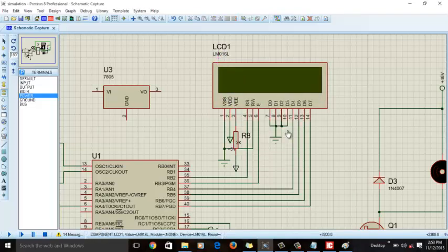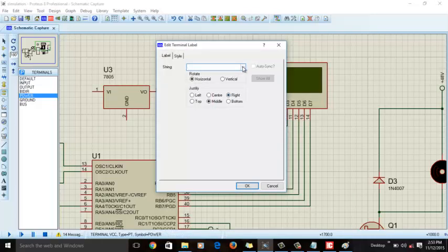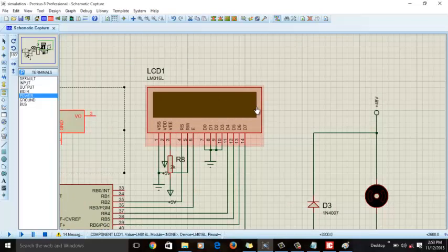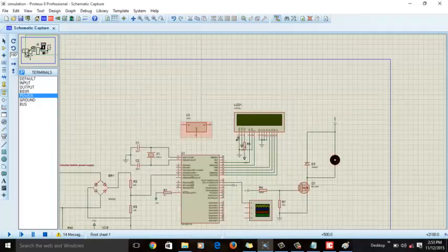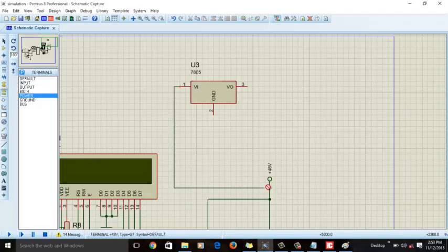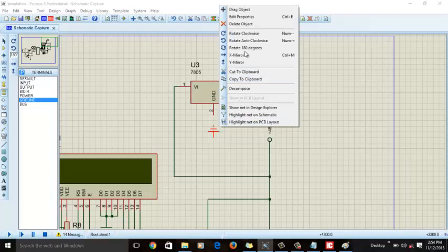You will need 5 volt with the microcontroller, and remember you can design the 5 volt power supply from your main 48 volt power supply by connecting the input voltage here and taking the output from here, connecting ground with the ground of your battery.